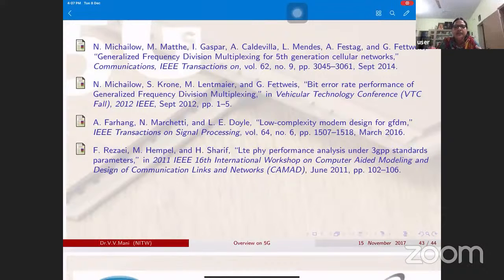The only thing is the complexity is increased, because we have to modulate those data with the prototype filter. Then after prototyping, we port that data onto the same carrier for M subsymbols. So similarly, if there are n carriers, on each carrier M subsymbols are ported at a time. That is the main difference from GFDM to FBMC.